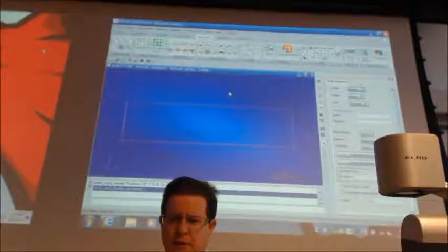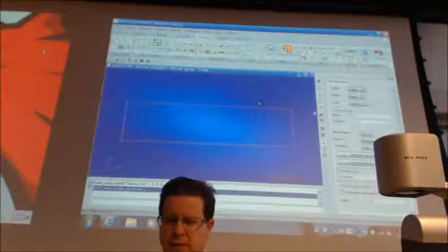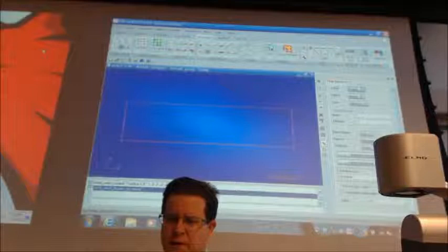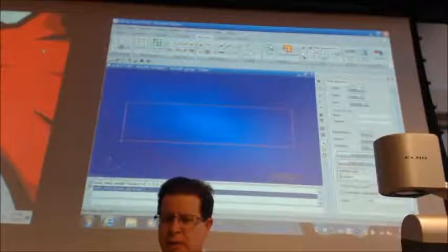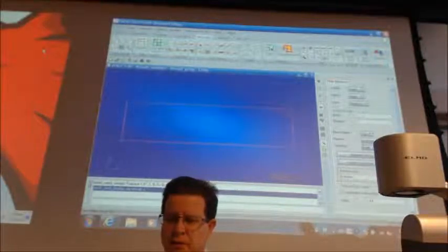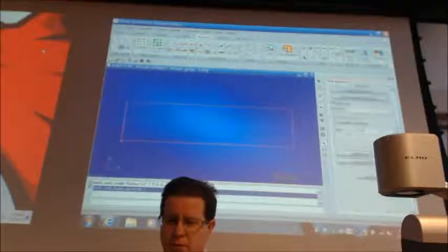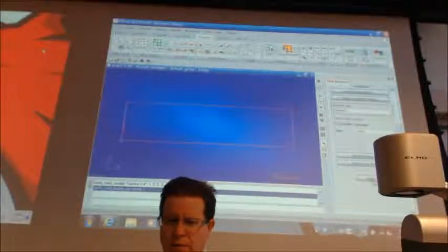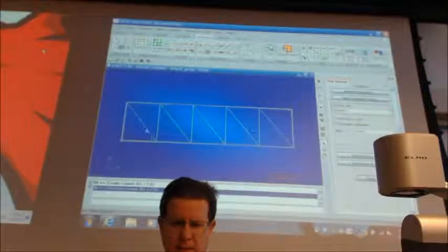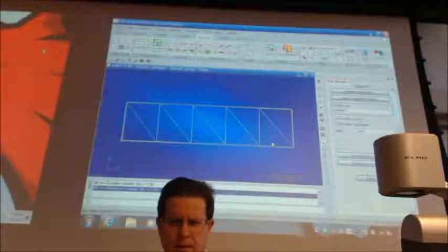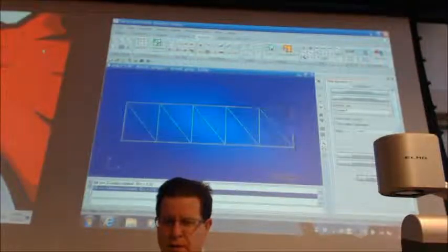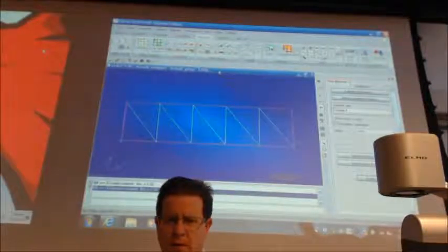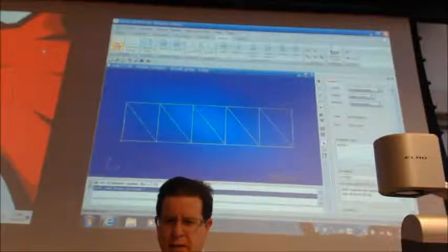Okay, so let's see, I need to create my surface again. This time instead of doing 3 nodes per triangle, we'll do 6 nodes per triangle. And we're going to surface 1, so we'll hit apply. Anyway, there's 6 nodes on there. So we should be able to go back to analyze.